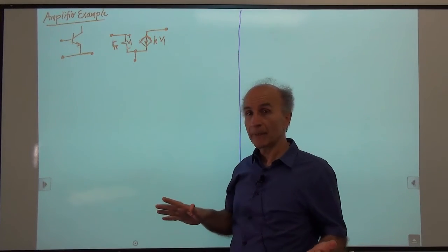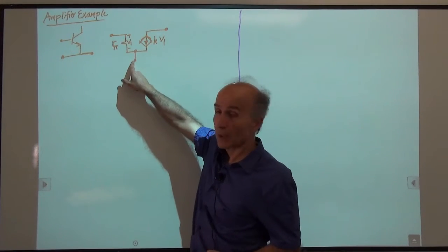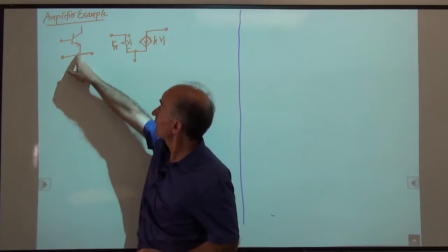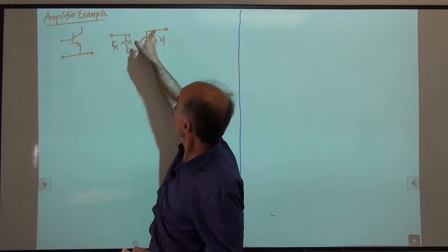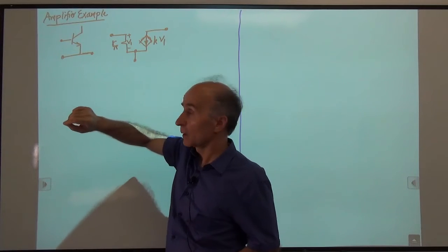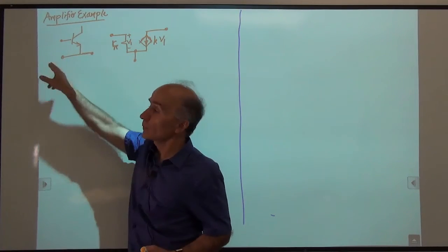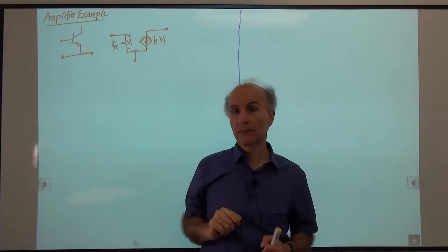That's all, right? And it just happens that these 2 are connected to each other, to one node, because that's what we have here. And this is another node, and this is another node. So this is an equivalent circuit of this. Keep in mind that this has only one node, even though I have drawn it as 2. These are all just one piece of wire.